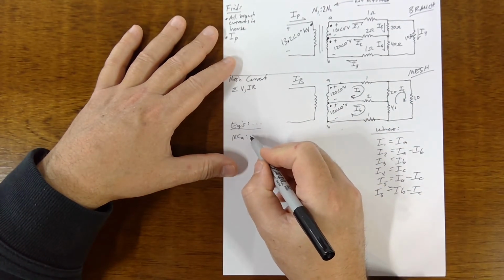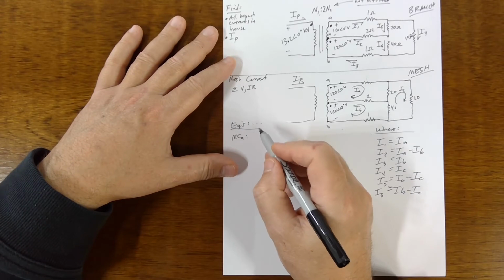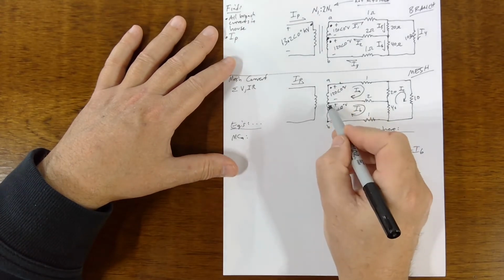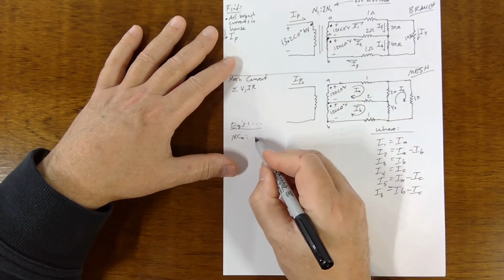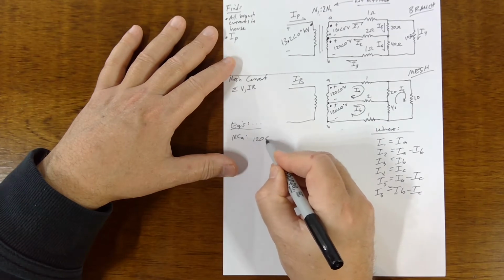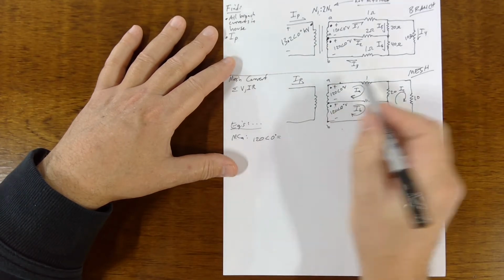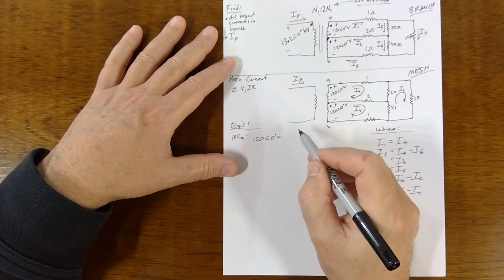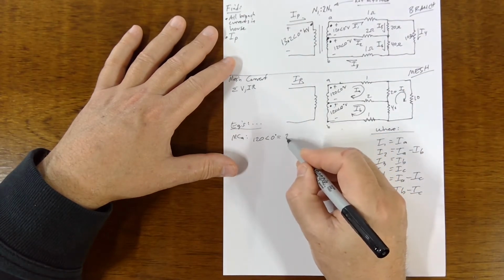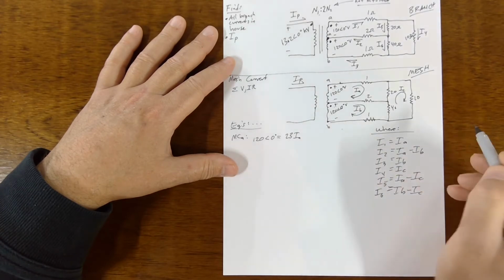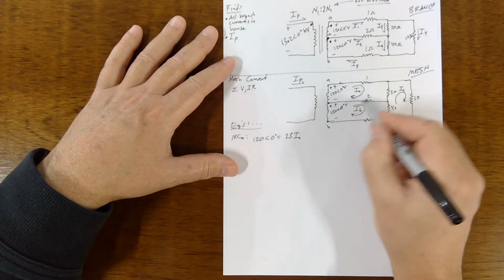Let's see. So what are we doing here? So we've got this voltage supply thing. I'm going to write it sort of solved for the voltage, but it's just a mesh current summing to 0. There's the voltage dropped across 1, 20, and 2, which is 23 IA. That's the main effect due to IA.